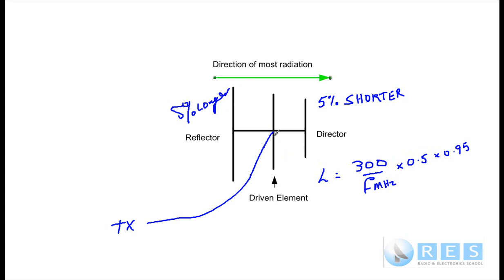The impedance you don't need to know, but it's fairly obvious. Imagine if you were putting resistors in parallel. If you had two 100 ohm resistors and you put them in parallel, you would get a total resistance of 50 ohms, and I hope you were able to answer that. Well, these dipoles are in parallel, and the impedance of one dipole is approximately 70 ohms, and we've got 3 of them in parallel. They're not connected electrically to each other.